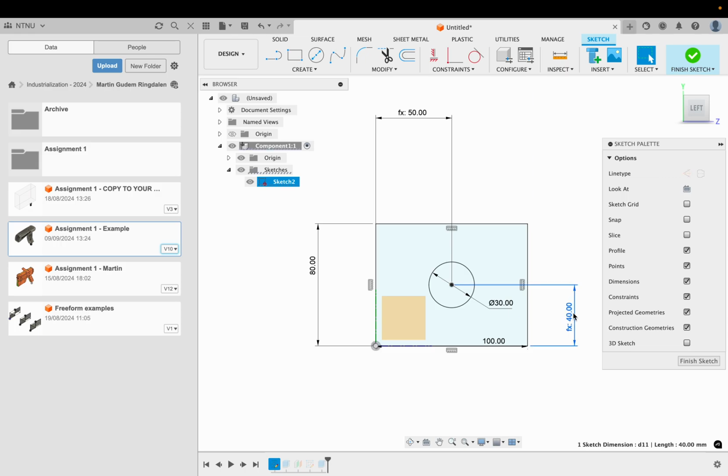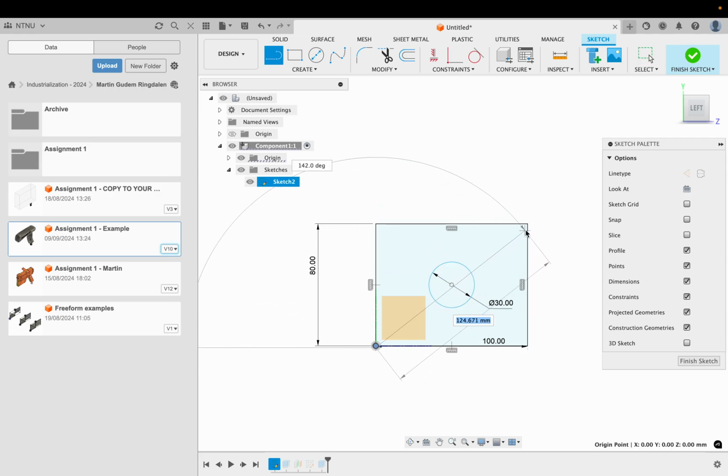But also in the interest of minimizing dimensions, it is better to just do, let's say we want this to be at the center. I will just do a line from here to here. That's a line, and oh, it's going somewhere. I need to constrain it. Now it's black, so now it's not going anywhere. Of course, I don't want this to interfere with my geometry, so I'm going to make it a construction line. And I do that by selecting it and hitting X. Then it becomes dashed.